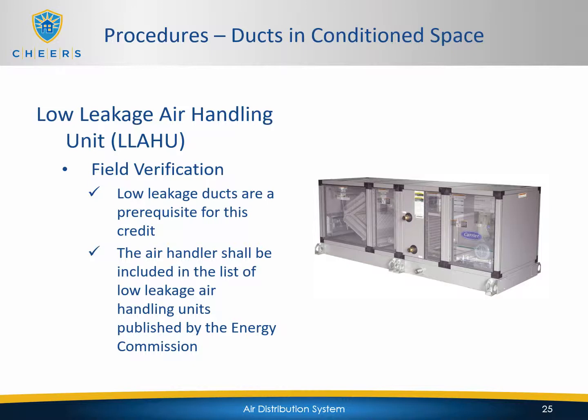For the low leakage air handling unit, for field verification, obviously the low leakage ducts are a requirement, and then the air handler shall be included in the list of low leakage air handling units published by the Energy Commission.